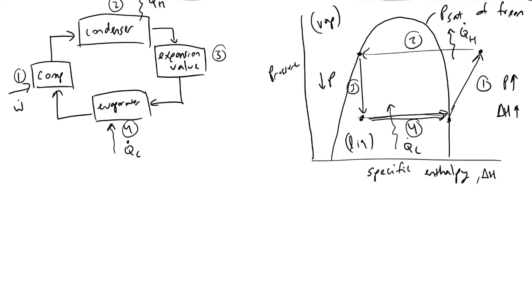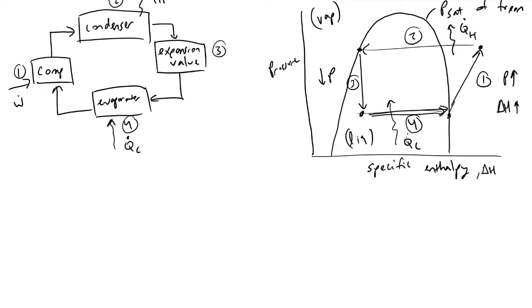If we were to perform some kind of energy balance on our system, if we just treat the refrigerator as some kind of black box, what we'd find is that we're going to have QC joules of heat entering per time. We're going to be supplying work into our system, and we are going to be rejecting heat to our surroundings at a rate equivalent to QH dot.